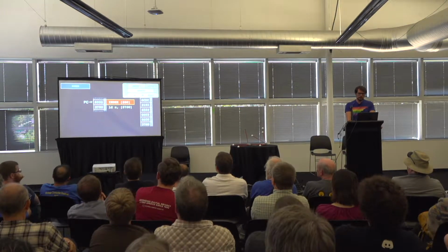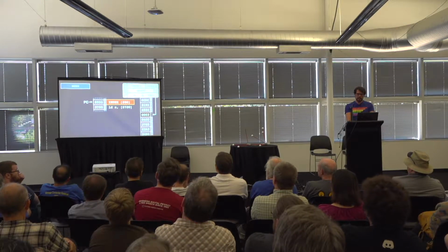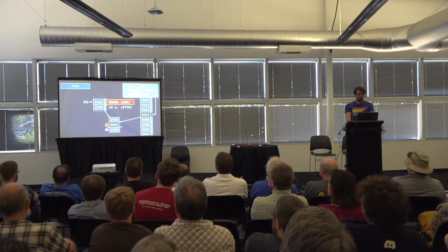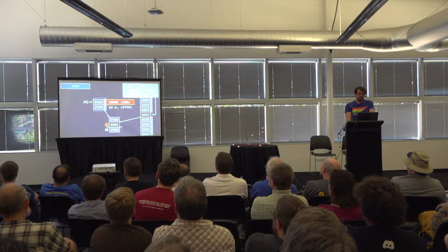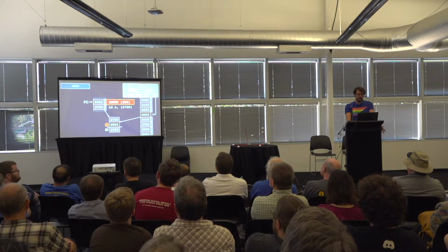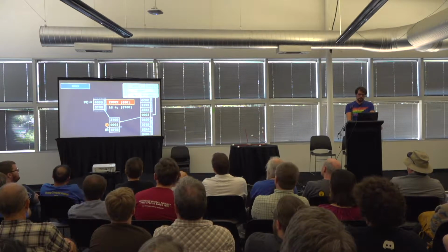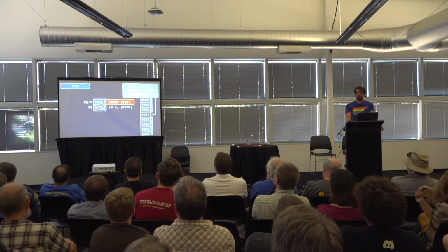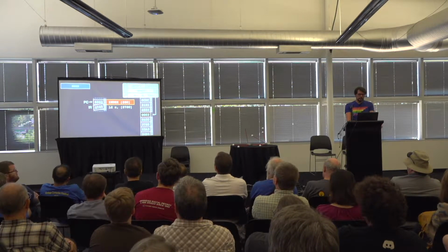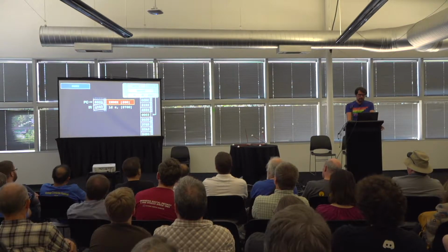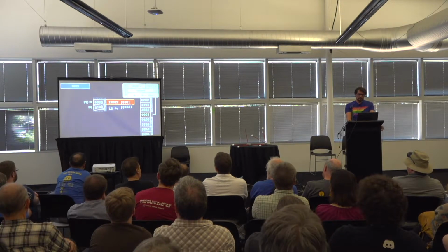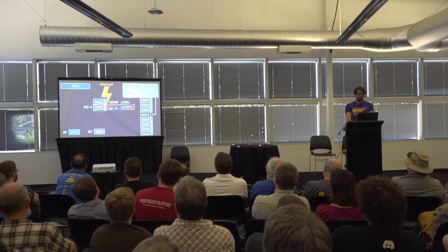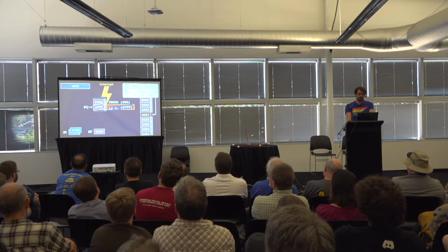The CPU reads from a given address, 080 in this example, then adds its value, 3, to the instruction code of the following instruction, 3700, which is stored in the internal IR register. It then uses the resulting instruction code, 3703, for the next instruction, which is load from 703, the effective address. If an interrupt occurs after the index instruction, that is no problem, because IR contains the effective instruction code, which will be saved into IR prime and restored at the end of the interrupt handler.